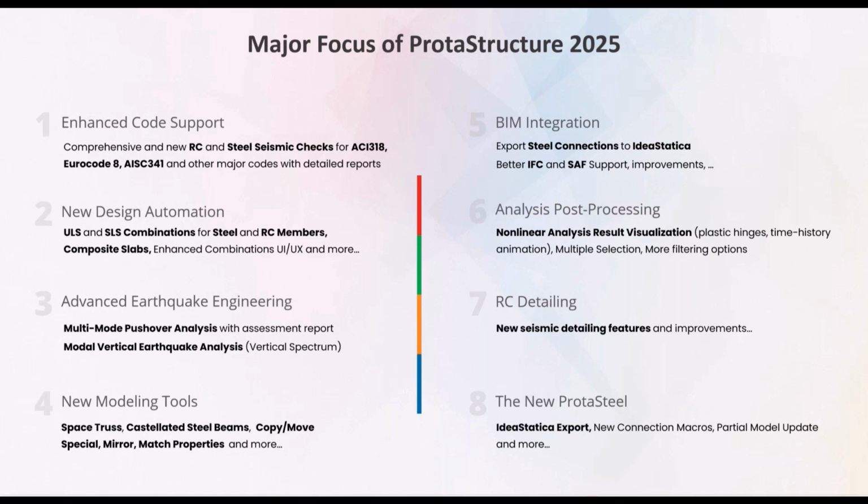And in terms of BIM integration, we now have better IFC support. Especially, we now have IFC 4 support, version 4. IFC version 4, of course, is more capable in collaboration, so we now support that. And most importantly, we can now export the steel connections to IDEA StatiCa.